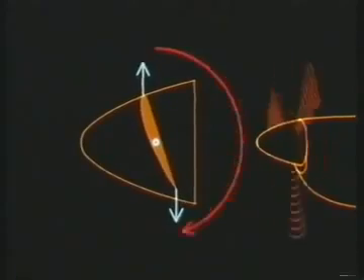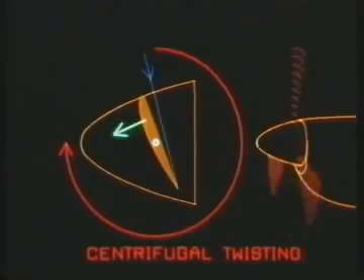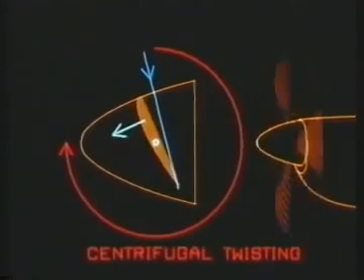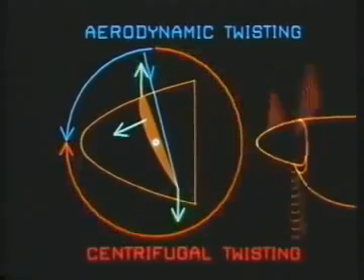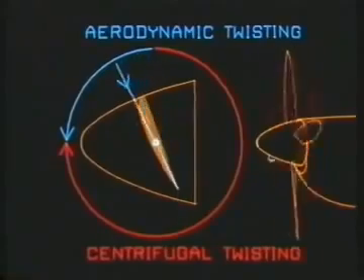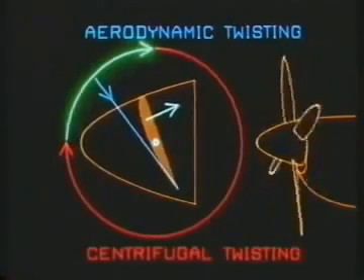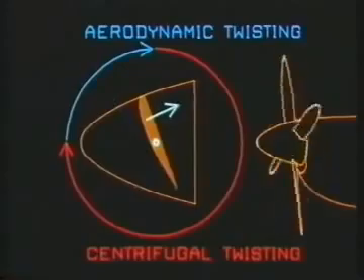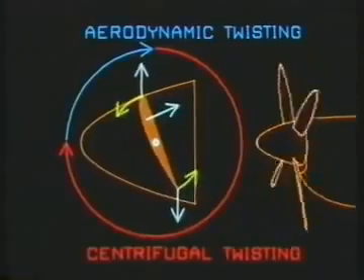The centrifugal twisting moment. The third principal stress is generated by the total reaction, which tries to turn the blades in the opposite direction, the aerodynamic twisting moment, which reduces the effect of the centrifugal twisting. But if the propeller is windmilling, this aerodynamic twisting will be reversed. So at high speeds, the combined stresses could overwhelm the pitch-changing mechanism and make it impossible to feather the propeller.